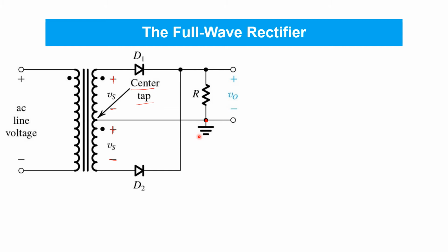That shows you that in the top half of the circuit, diode D1 is connected to the positive side of Vs, whereas in the bottom half of the schematic, we see that diode D2 is connected to the negative side of Vs. So that's the key point that's going to make this into a full wave rectifier. To understand its operation a little better, let's again consider what happens in a few different scenarios.